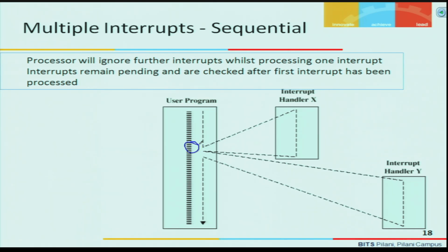So a hardware circuit is always faster than software, so that's why hardware polling is better than software polling. Whatever mechanism is there, usually daisy chain is used in most of the systems. But whatever mechanism is there, first the device which responds to the interrupt acknowledgement signal by the processor will provide the vector or address.